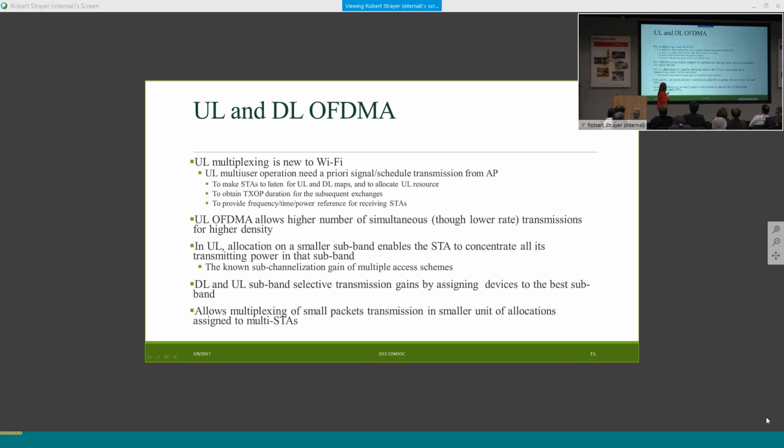Now another benefit of this trigger frame is that when the station receives the trigger frame, through the preamble, they know what their timing offset is, what their frequency offset is. So when they transmit uplink after the trigger frame is done, station ABC knows that it's their turn to transmit uplink. They adjust their frequency offset and timing offset based on what they receive from the prior transmission. So this adjustment of time and frequency offset needs to stay valid. So it has to be within a really short time. The response has to go back. And Wi-Fi always has a very restricted time constraint as opposed to LTE or WiMAX. Those are synchronized systems.